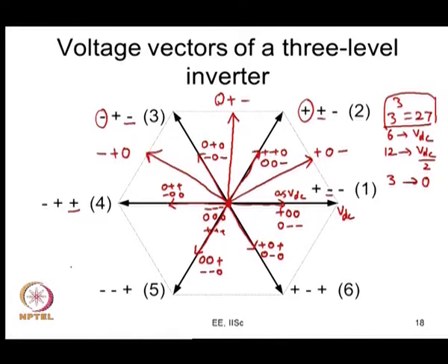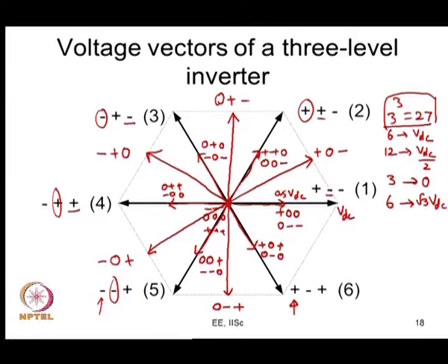And here it is plus, and here it is minus. It is the y phase that is switching. So, you consider minus 0 plus, and that would be producing a vector like this. And here once again you have minus minus plus switching to plus minus plus. So, in between you have 0 minus plus, and that produces a vector like this. So, you see that you have 6 more vectors, and these active states produce active vectors of length √3 VDC by 2.